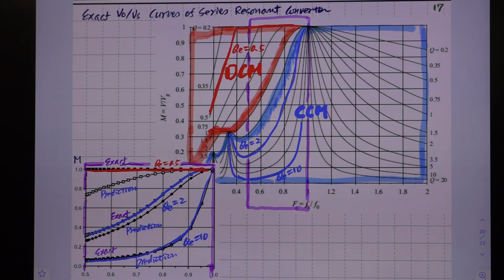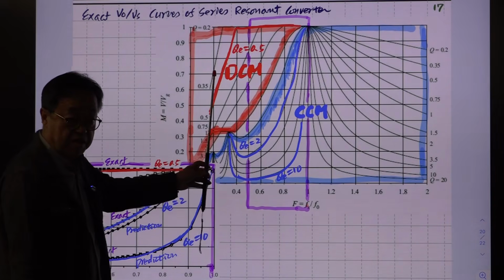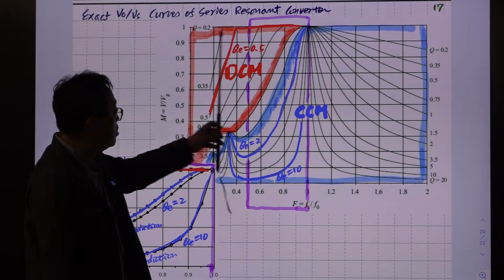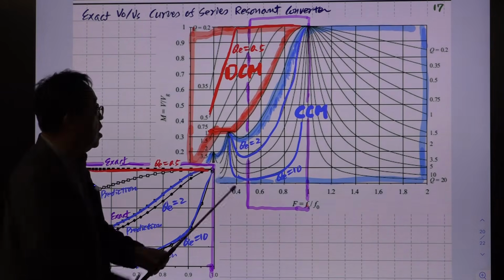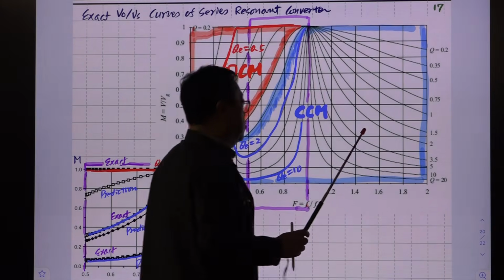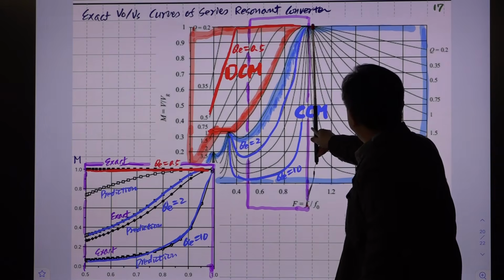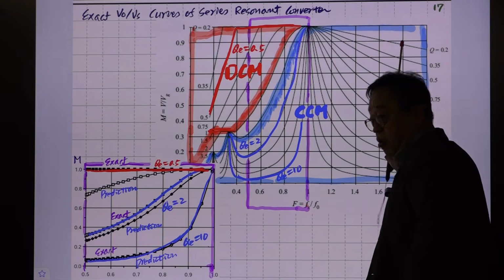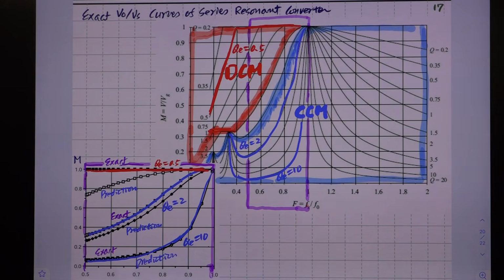So many people studied the operation of this resonant inverter or converter in this region, using phase plane analysis, state plane analysis, very complicated analysis. But for your case, you don't have to worry about this one. So always select operation above the resonance. Then you have this characteristic which is closely predictable from that simple AC model. So that is one thing.